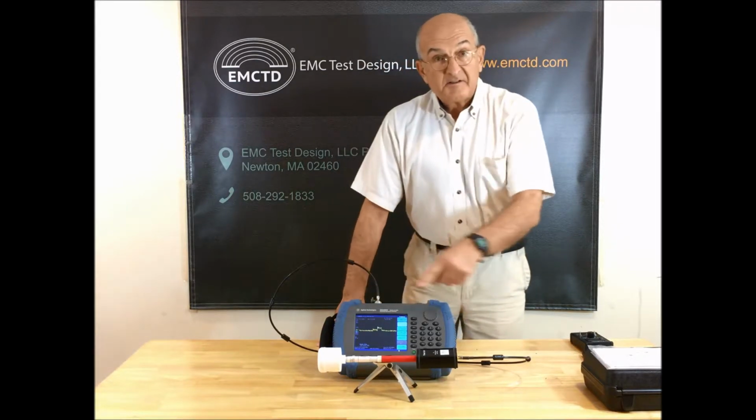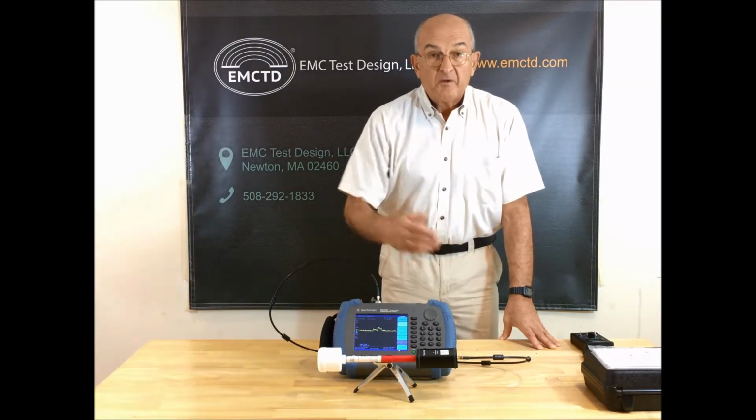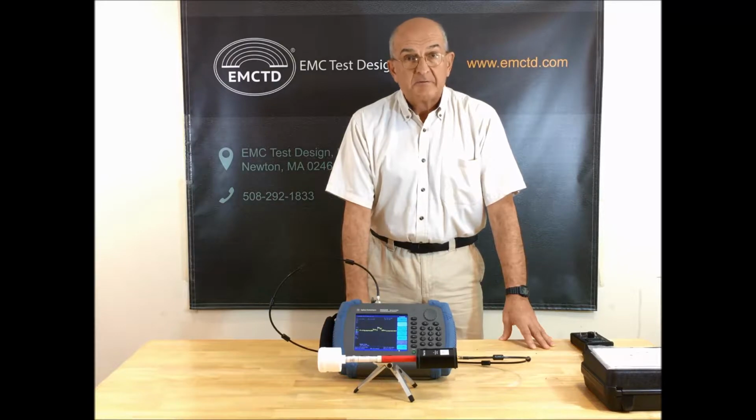Inside the head, you have three XYZ antennas orthogonal to each other, and they are being switched in sequence. The resulting signal that we can get gives us RMS value for any orientation of the head with respect to electromagnetic field. Because in order to get stable and correct measurements when spectrum analyzer is sweeping, it needs to cover all orientations of the antenna axis. There is a limit how fast you can sweep this antenna. If you get unstable signal, you just need to sweep slower.